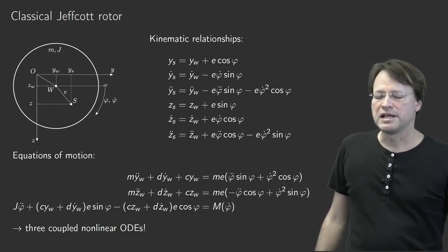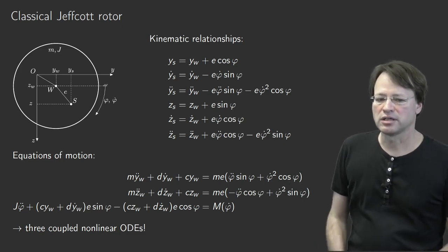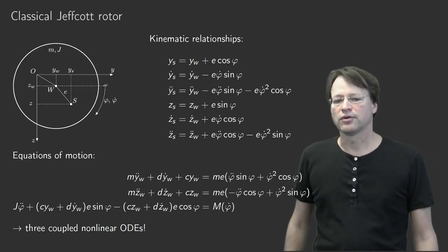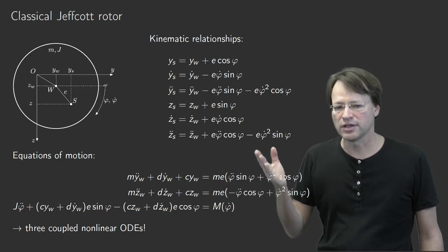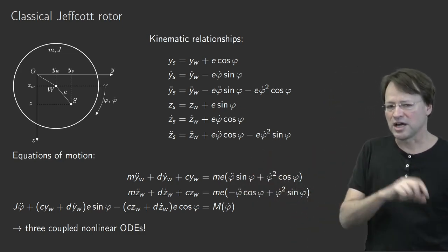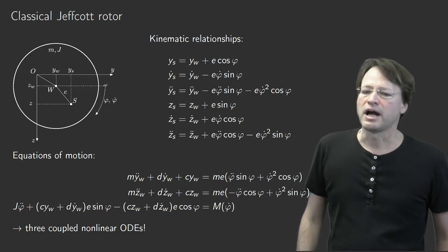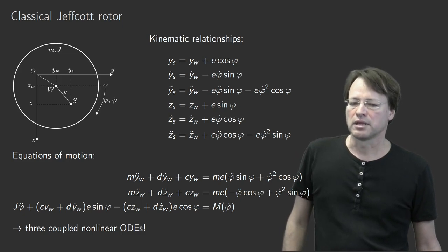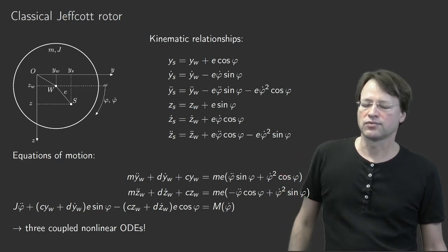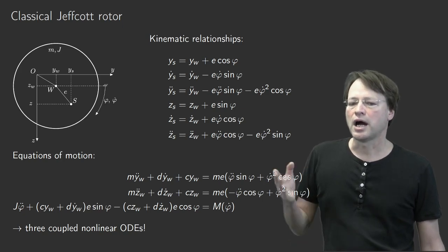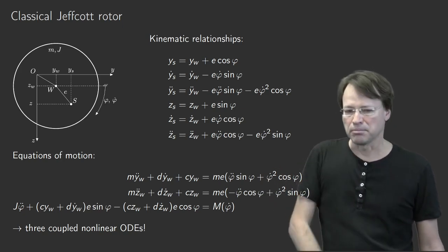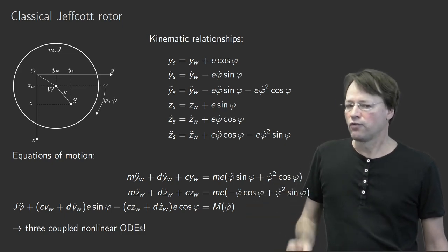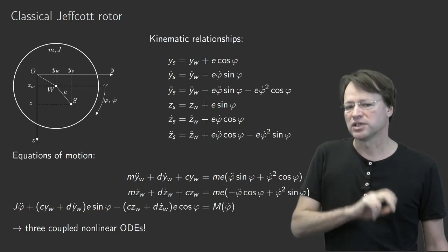So for the moment, let's assume that there is stationarity of the motion, and then I will show you that for this case a decoupling of this equation of motion is possible, and not only a decoupling, I'm able to solve the first two equations because they then represent linear equations for a single degree of freedom oscillator under excitation by a rotating imbalance. And from the last equation we will derive conditions for such a stationary solution to exist.